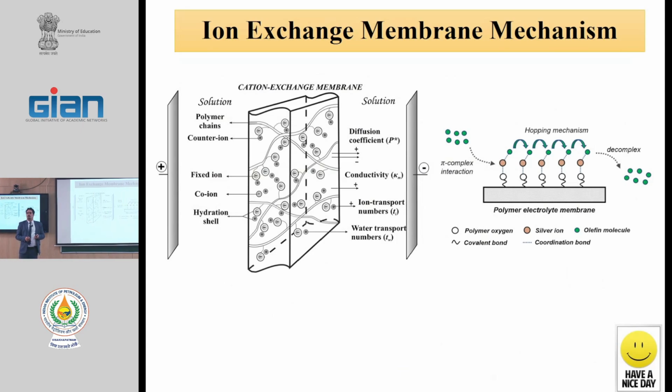And as the final slide, we have ion exchange membranes. In ion exchange membranes, we want to pass cations through the cation exchange membrane, and anions do not pass. For example, in this slide, for passing of positive ions, we need negative functional groups on the membrane structure.